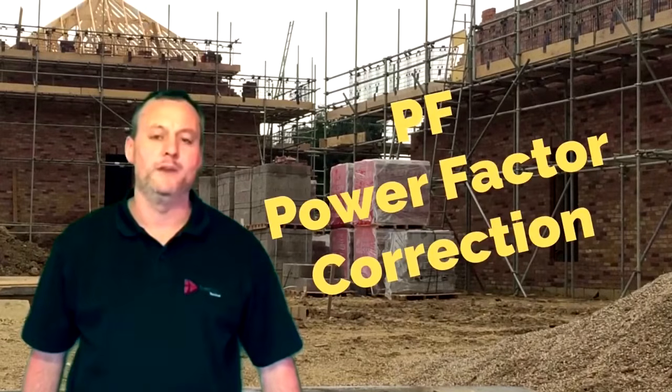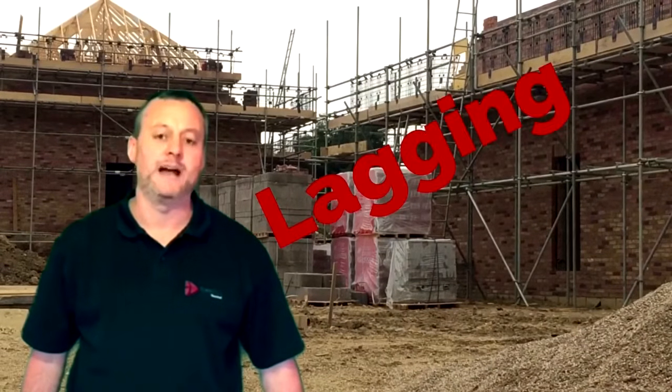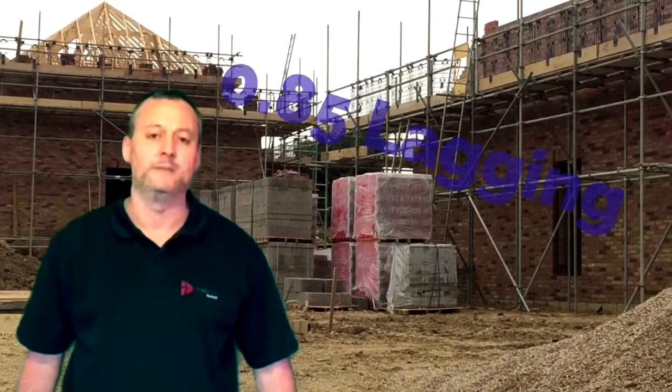Again, we need to remember that a power factor will be a number between 0 and 1. If the power factor was 1, we said that the power factor is in unity. In other words, true power and apparent power are the same. We don't like to leave circuits at unity, at 1. We like to have a slightly lagging power factor, so our number will be less than 1 between that and 0. So often we hear power factors of 0.85 or 0.9 lagging as a power factor.